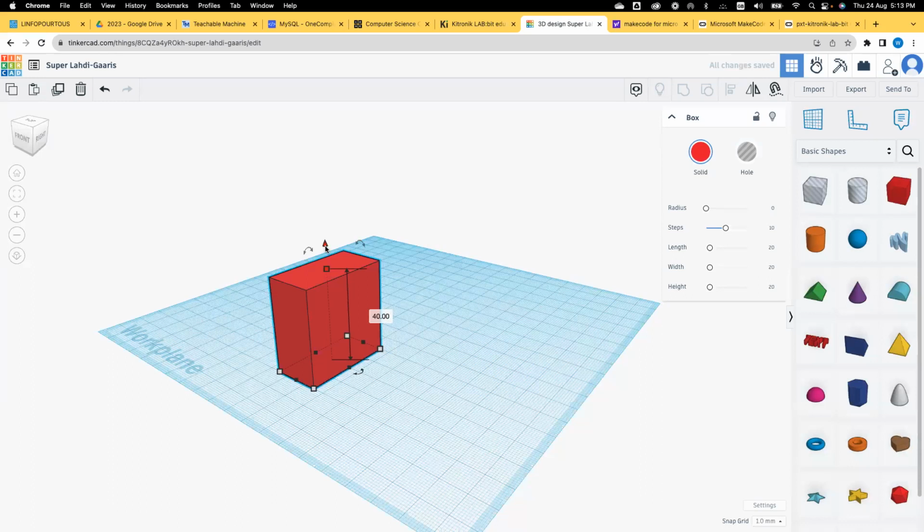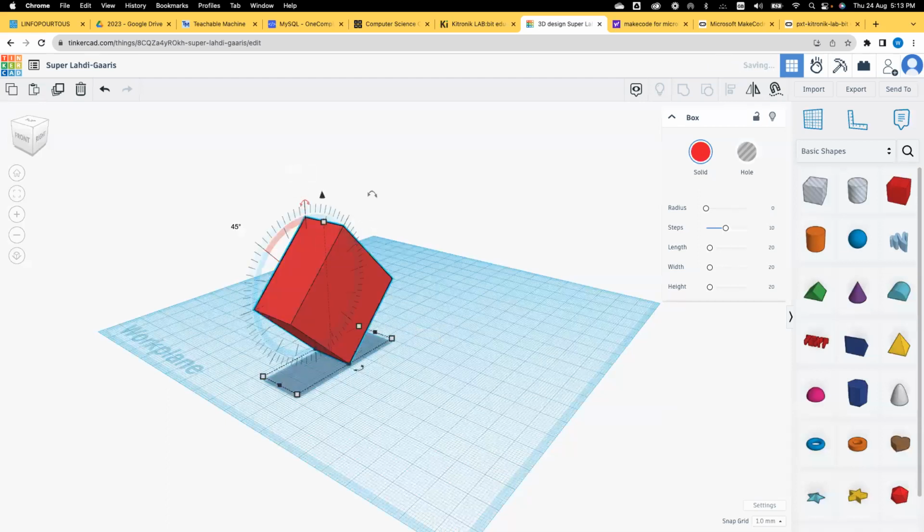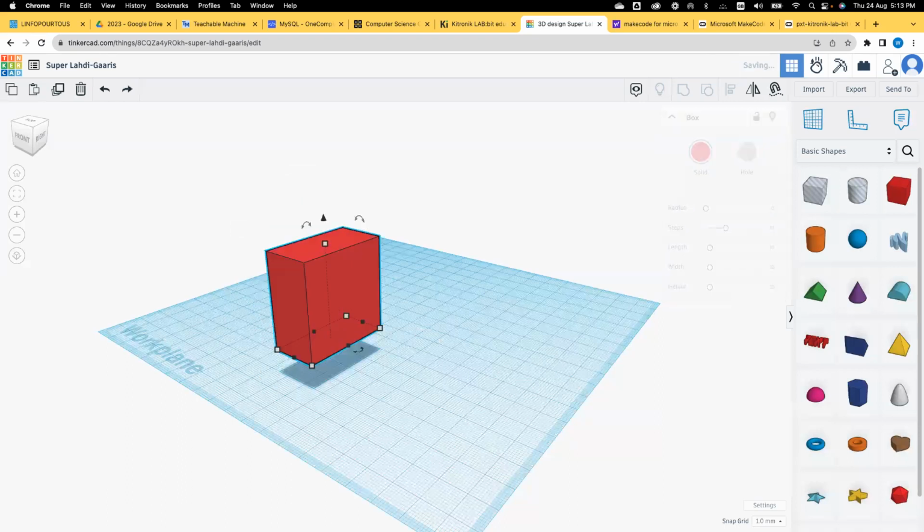This black triangle is to raise my object from the work plane. So it's very important. You click once, and from here, if you type 10, for example, it's raised by 10 centimeters. Of course, here you can click to rotate. So I believe that all those features are clear for you.